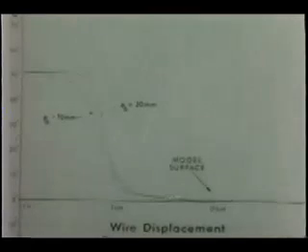We have seen that in rarefied gas dynamics, familiar features of continuum flow disappear as the Knudsen number increases. These are replaced eventually by the distinctive features of free molecule flow. In this extreme, the nature of collisions between gas molecules becomes unimportant, and the nature of molecular scattering at a solid wall becomes dominant.